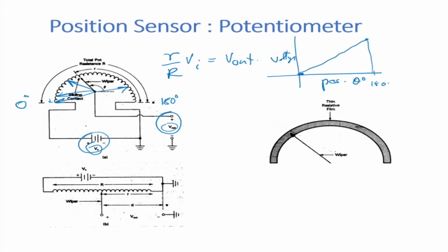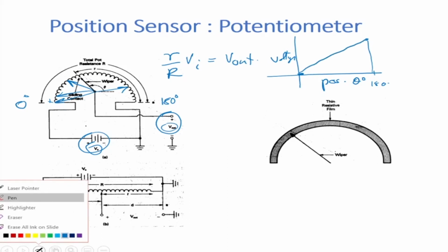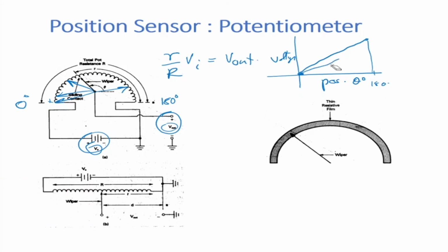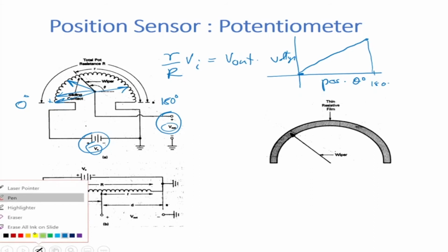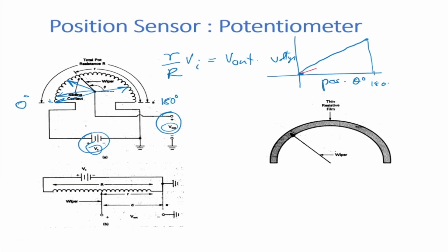Theoretically, but normally it will not be a straight line; it will have a slightly curved shape like this. Why is that so? Because resistance is affected by a lot of things. It will be something like this, and this is called the non-linearity in the system, which is sigma. Why will it not be exactly a straight line? Because resistance change is affected, number one, by temperature.